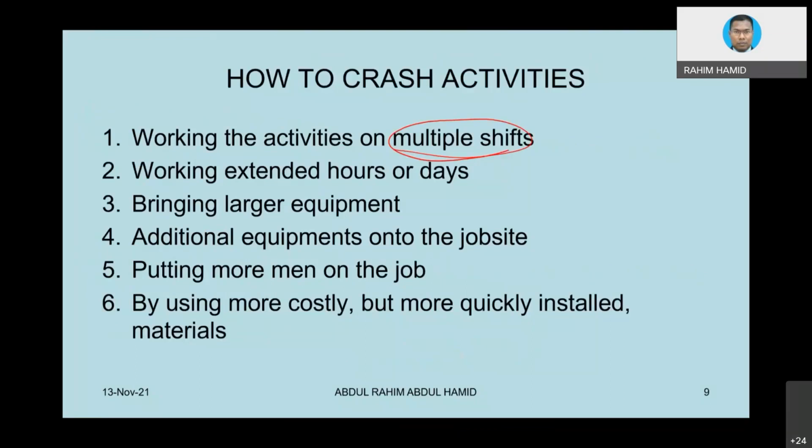Working extended hours, instead of finishing the job at 6 p.m., maybe you can extend a little bit more, 1 or 2 hours, okay? Bringing larger equipment, instead of using a small capacity machine, why don't you bring bigger equipment that can carry a bigger load? Additional equipment, more equipment, more machines, more men. And then lastly, coming out with an alternative design, IBS for instance, instead of using